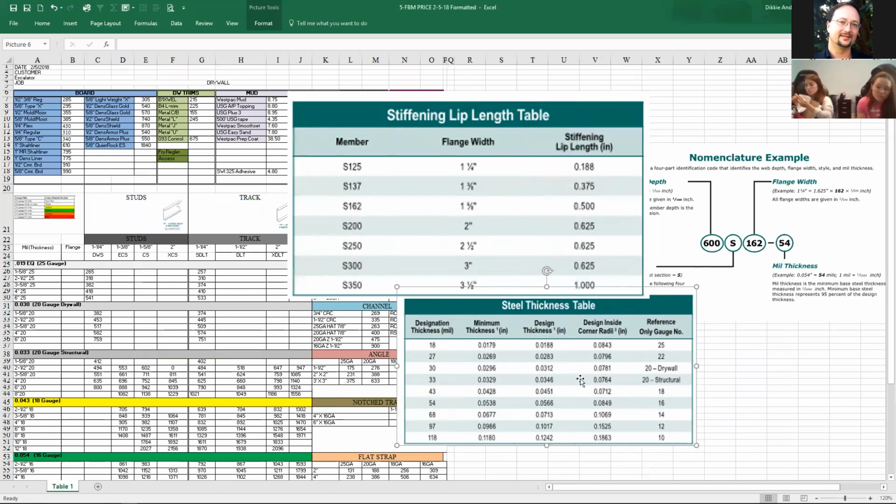For steel stud gauges, for exterior, meaning the structural stuff, traditionally I always submit 16 gauge, unless they call out the gauge thickness. Unless they note it needs to be 12 gauge, then I'll submit 12 gauge. I traditionally never submit 14 gauge, because I'm usually trying to push it down to 16, or elevate it up to 12 gauge.